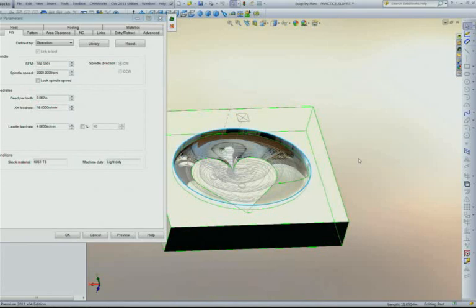Then it'll step back up from the bottom of the pocket, and at that point, it cuts out only the material that's left from the original roughing at the bottom of the pocket. Here, I'll increase the surface footage for the roughing for Volume Mill. With Volume Mill, you can typically double or triple your surface footage. So I'm going to increase it.